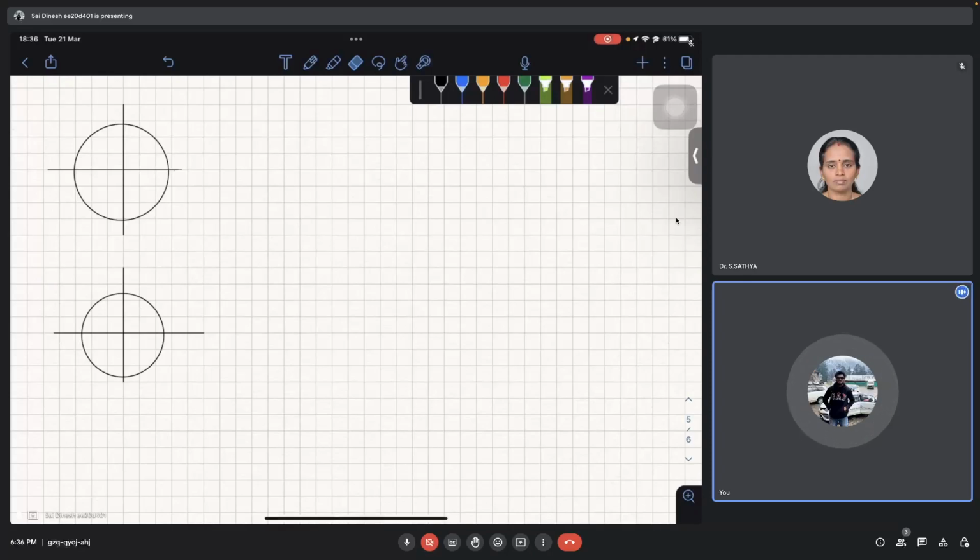Okay, let's see. Can you tell me? So let's say we have only a single pole to place, and we need a low pass filter. Where do we place that? Since we need a high gain at the lower frequencies, we place the pole at a lower frequency. So let's say we have a pole over here.